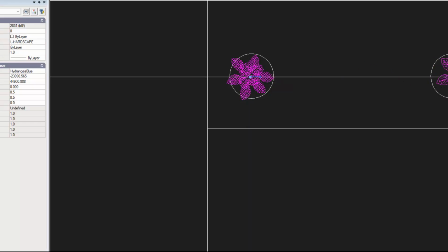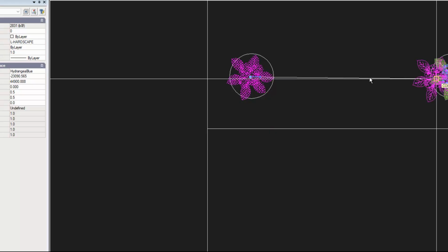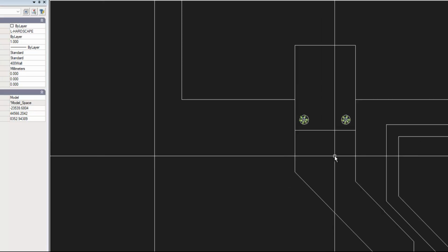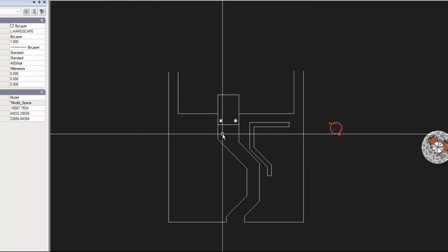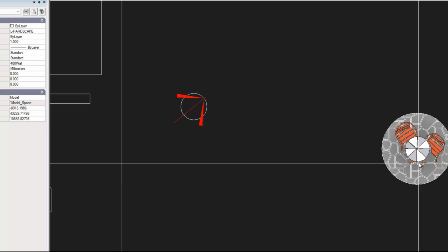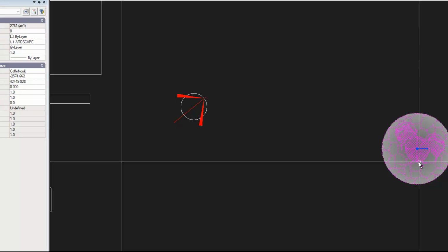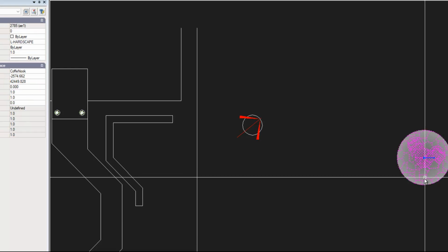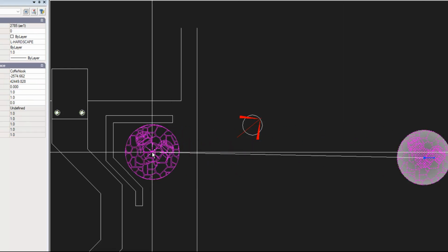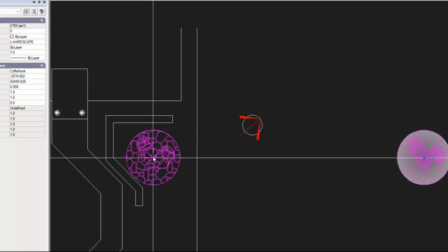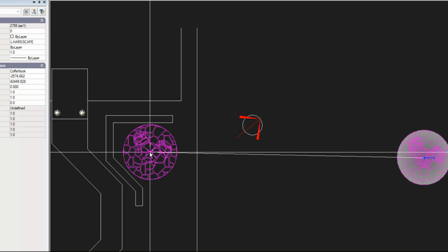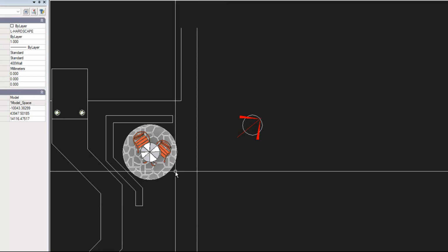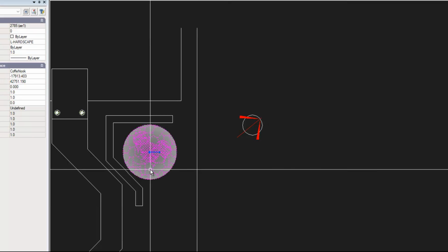So we save enormously on our drafting time by using symbols and things from the library, but we can also use symbols from other designs. And this is one that I extracted from another design, and it's called Coffee Nook. And so we can pick it up, move it by its insertion point there, and we'll position it like so. So there we have a little table, a circular area with some hatching on it.